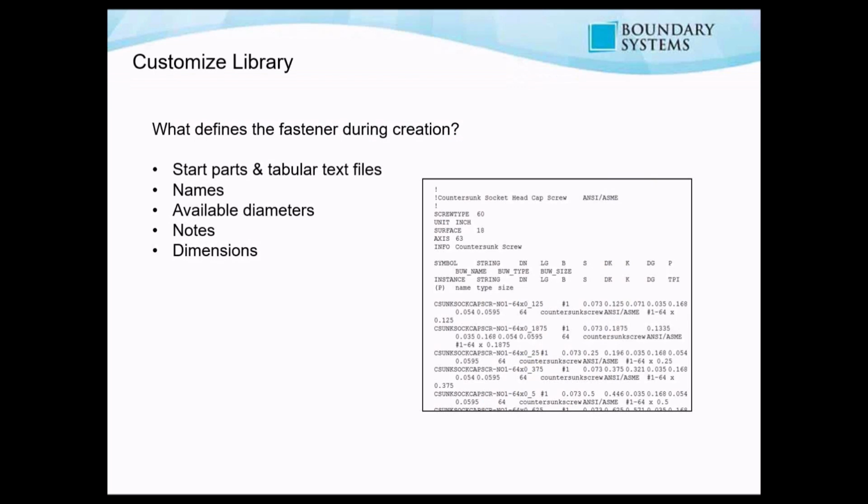Okay, and then those parts are defined in a text file, and that text file is used to drive that particular part. So it's going to change length. It can go from, let's call it, an M5 to an M6 and so on. So the structure of these text files is actually driving your library. That's just an important thing that you need to realize.